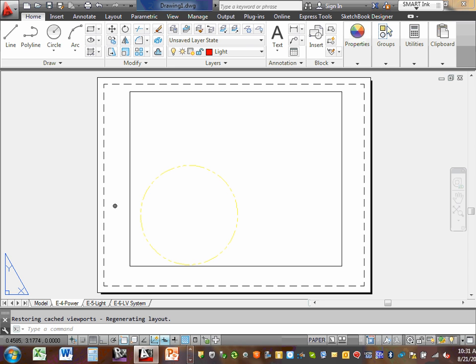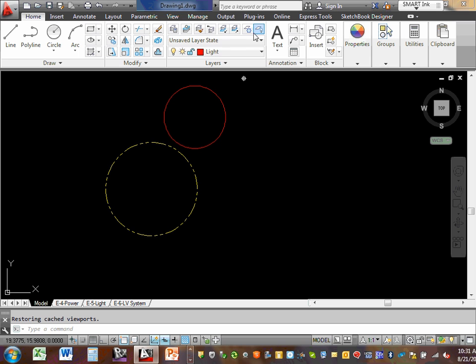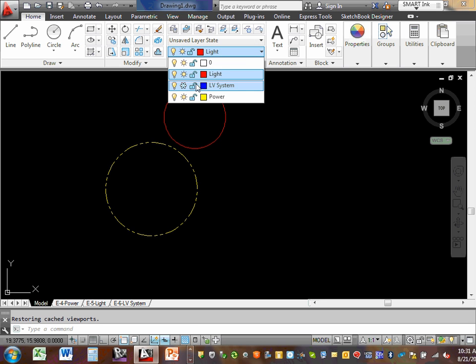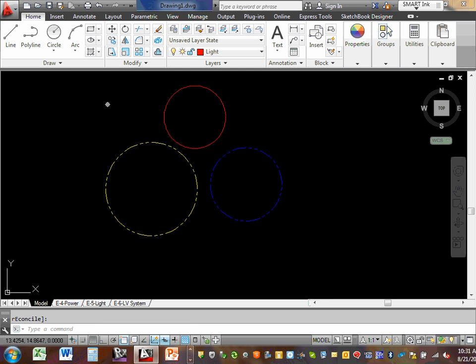So yeah, we'll just try them. Let's go back again and turn it on. Freeze in that layer, most likely will allow you to print it. So it's not showing here, but it will print. But that's confusing though. It will confuse you a little bit. So if you want to not see it here but print it, then you will freeze it.